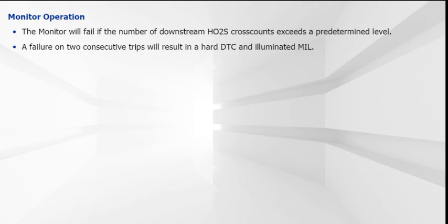Important: be aware that a leaking exhaust system can affect the stability of the oxygen sensor signals and ultimately lead to a false monitor failure. In addition, the use of aftermarket components, such as a replacement converter or O2 sensor, may lead to a false DTC.